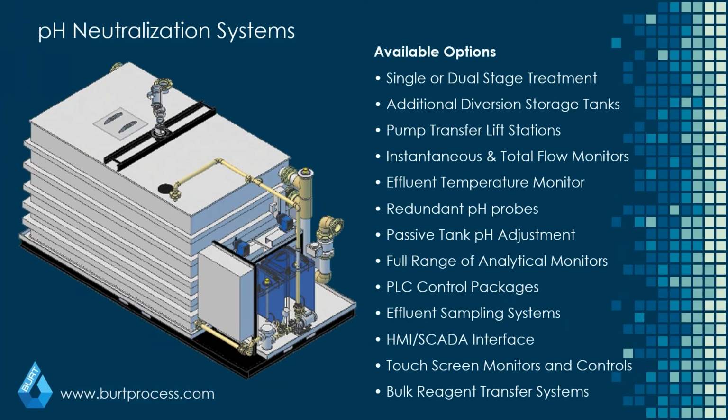But they're very big. They come in single and dual stage configurations. They can have lift stations, equalization tanks, large PLC controls, and on some of the bigger ones, that tank can range to be 13 to 15 feet long, which doesn't sound that big when you're thinking about a shipping container. But putting the tank in, the reagents, the control panels we're going to see, everything needs to be laid out in a way that is ergonomic and practical, and also allows for other ancillary equipment which may be required for the system.